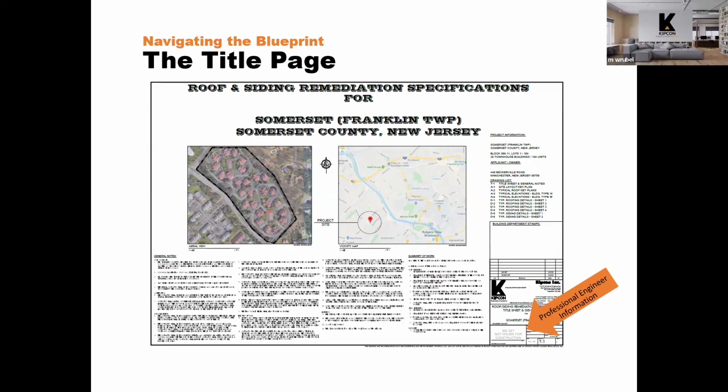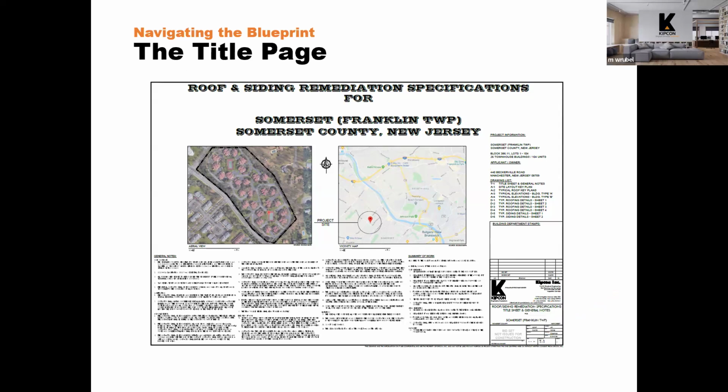In this particular title block, it says bid set not for construction, not issued for construction. So it's just in the stage of being bid. There may be changes to it. It's not ready for construction yet. So that would also be noted in this area here in the signature block. If it's a review set, it might say in big letters, just review set, not for construction. And there's a revision block, as I had mentioned earlier.